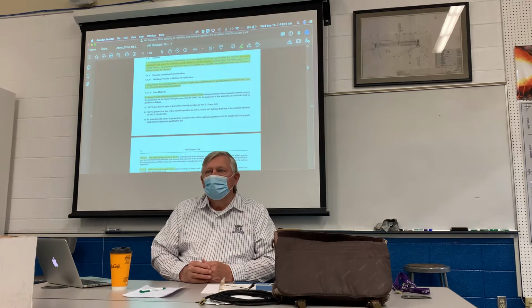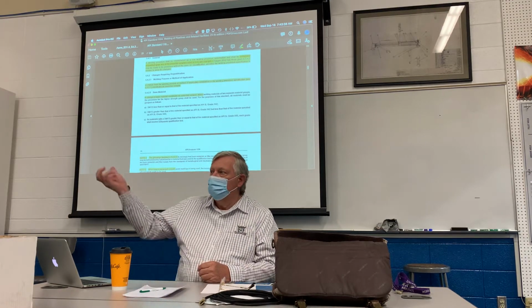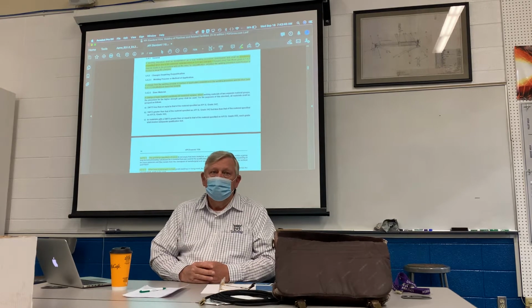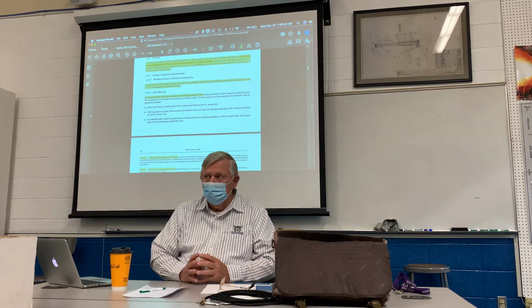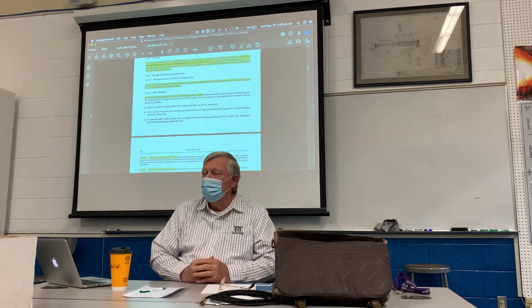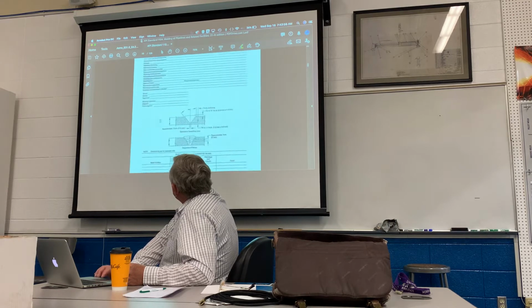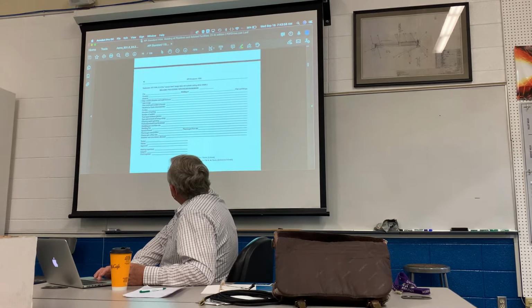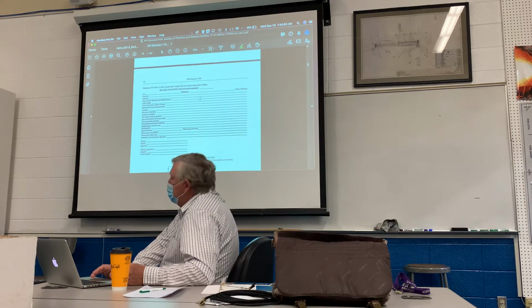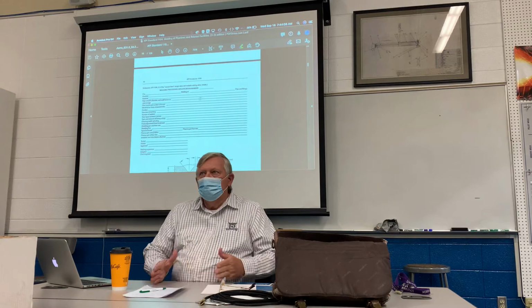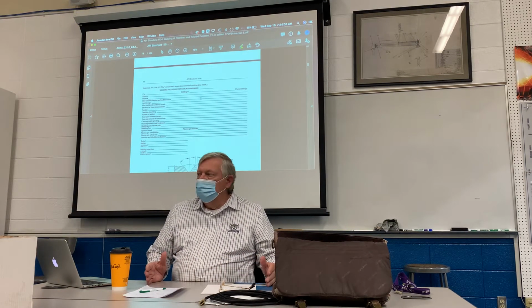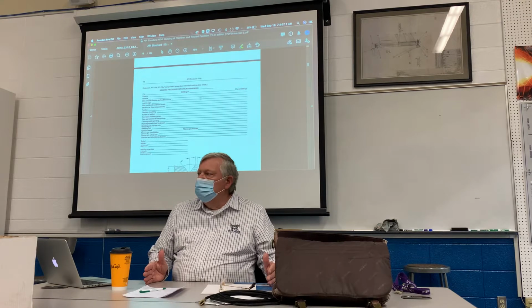You could say, I'm going to do SMAW welding of X42 pipe. Right? What are you going to use? Well, I'm going to use 60-10 in the root or 70-10 in the root, and I'm going to use 80-10 on the fill and cap. So those would be items that you would put here. Pipe outside diameter and wall thickness. You choose your pipe size, and how do we determine pipe sizes? We talked about that a little bit. Below 12 inches.